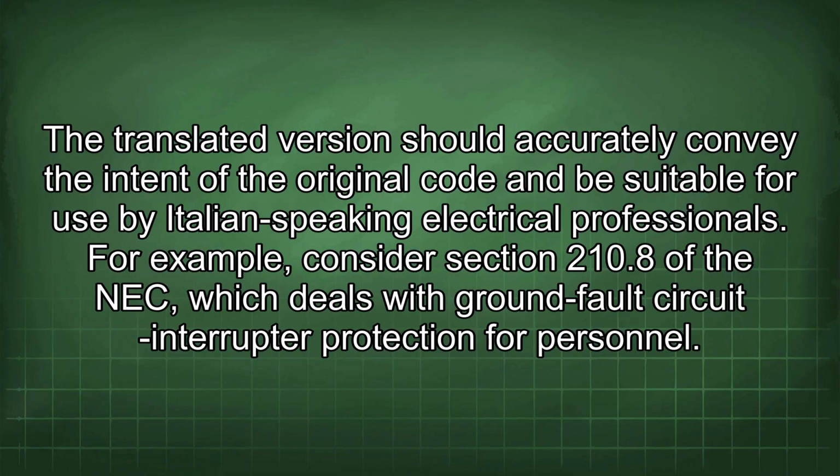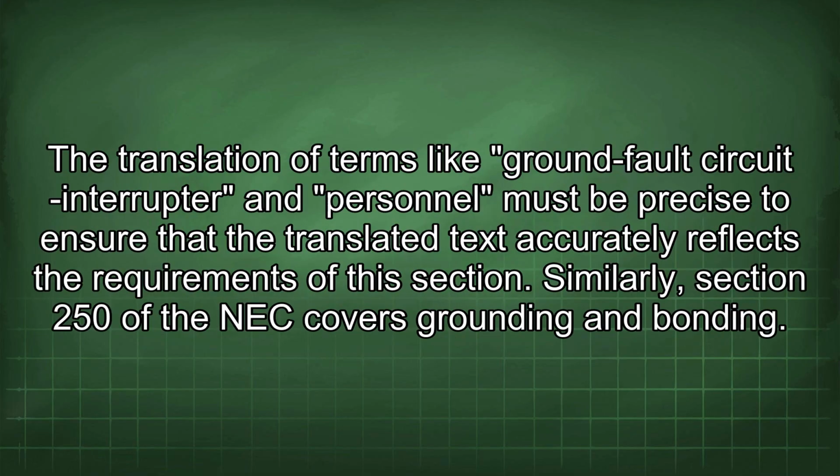For example, consider section 210.8 of the NEC, which deals with ground fault circuit interrupter protection for personnel. The translation of terms like ground fault circuit interrupter and personnel must be precise to ensure that the translated text accurately reflects the requirements of this section.